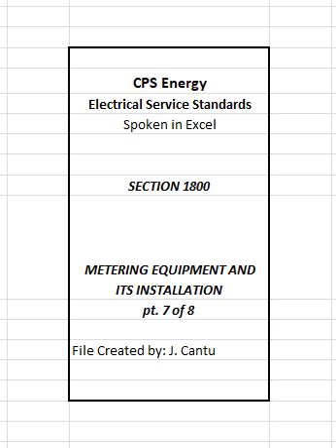2. Service may be designed with minimum 600 ampere rated modular metering equipment. Modular metering equipment shall be capable of supplying 6 meter positions. Where more than 6 meters are anticipated, a main disconnect shall be incorporated into the design of the modular metering equipment, refer to figure 1814.